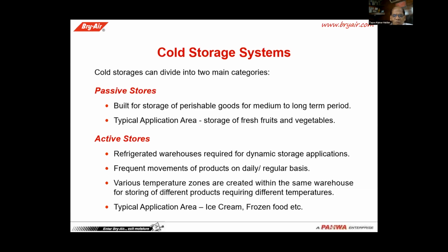Generally in active cold storage, there are various temperature zones. Earlier, in our old days, there was a cold storage maintaining a certain temperature. But nowadays, a cold storage has various zones. Some, say for ice cream storage, maintain minus 25 degrees centigrade. Frozen food, maybe minus 20 degrees centigrade. Some areas maintain 2 degrees centigrade.